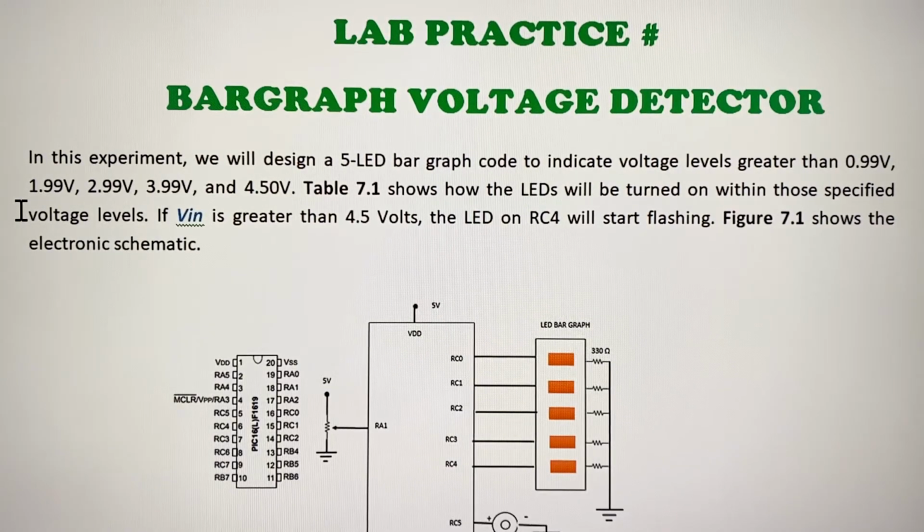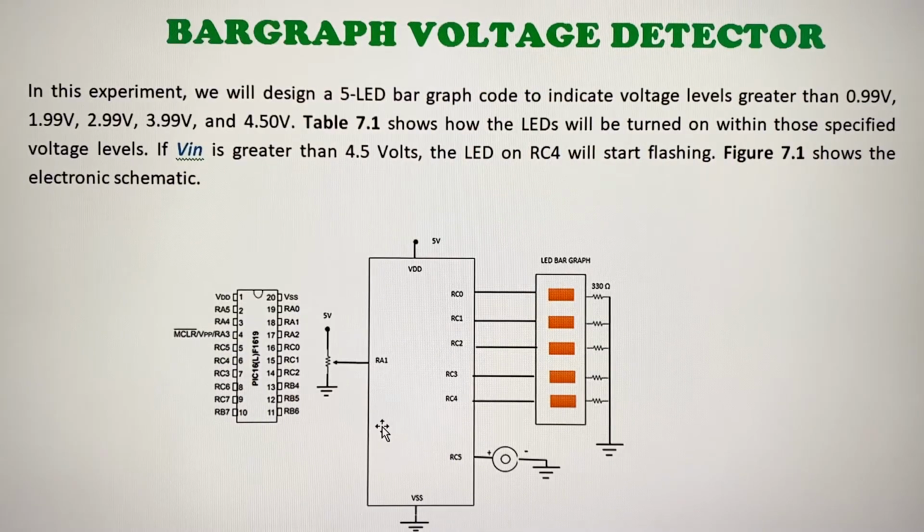Hello everyone, this is Professor Jimenez, and today we will design a bar graph voltage detector based on the A to D converter. And right here we have the PIC 16F1619, which will be reading a voltage input and controlling an LED bar graph with 5 levels.